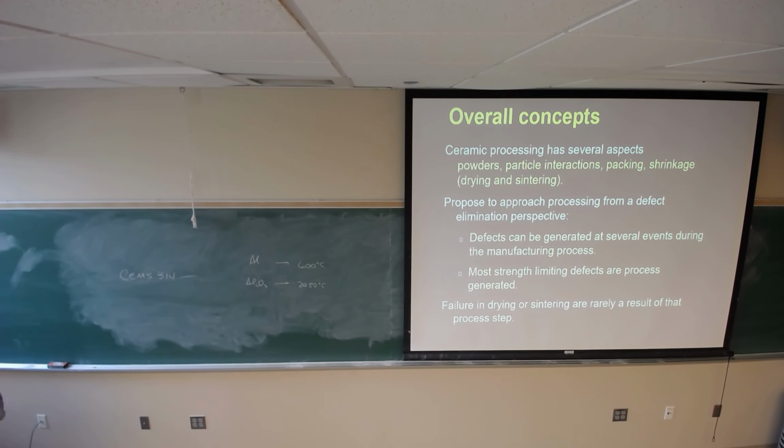The reason that we do that is that we have data that indicates that during the sintering process, the flaws don't go away. In other words, the flaw that you introduce in the process is the flaw you have at the end when the system is fully sintered. And the conventional wisdom says that in sintering, we eliminate those defects, that the pores are the defects that control the strain. And what we demonstrate is that that is not true.